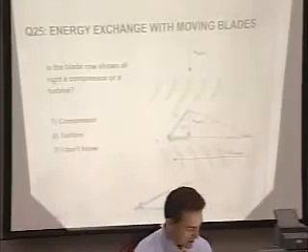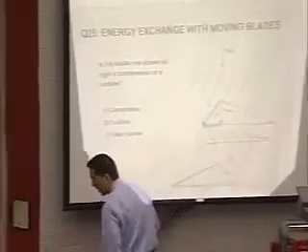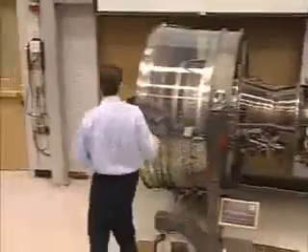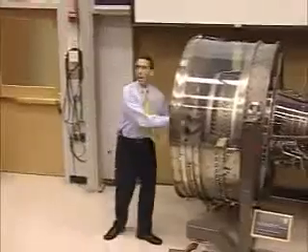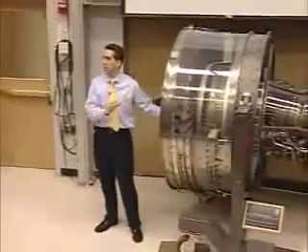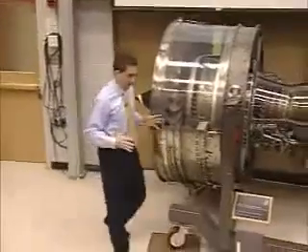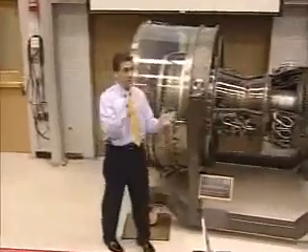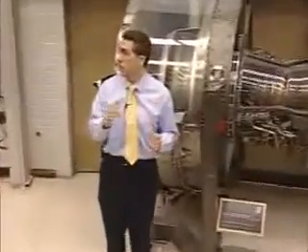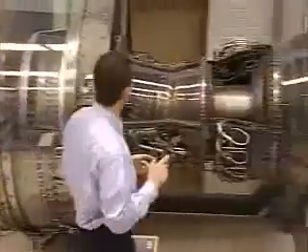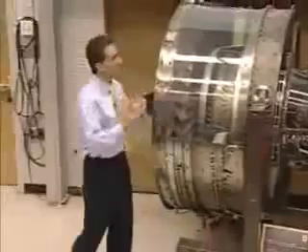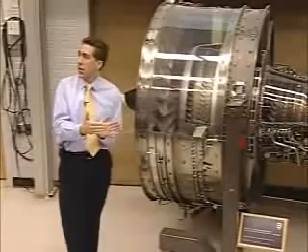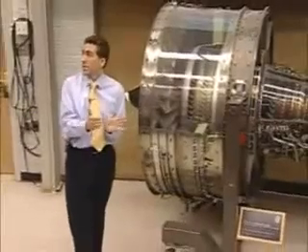So again, I would just think about yourself as a fluid particle, and you're traveling through this engine. You come in and you've got no angular momentum, and then whammo, you hit these blade rows. And now your flux of angular momentum is changed. You have some positive flux of swirl going through the engine, and each one of these blade rows keeps changing that as you go through. And it's only the moving ones that add the energy. The stationary ones just convert it from swirl back into the axial direction, and in doing that, convert it to internal energy.